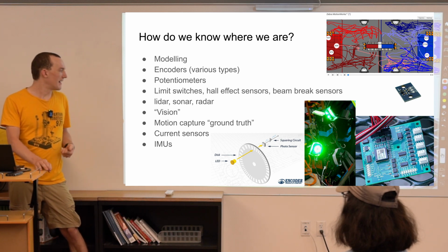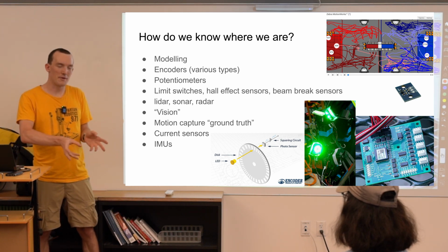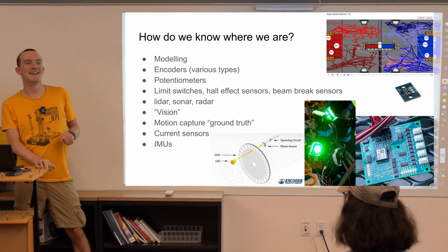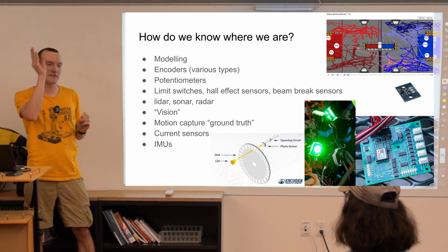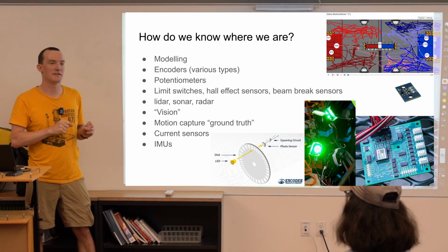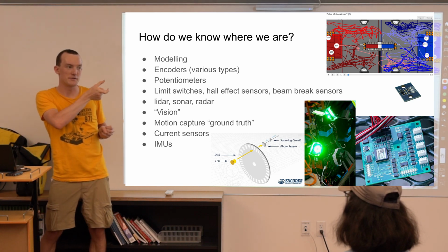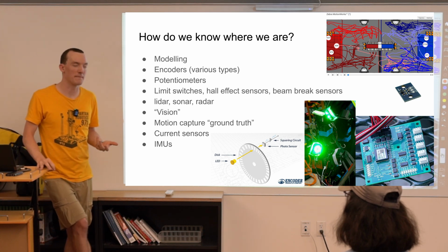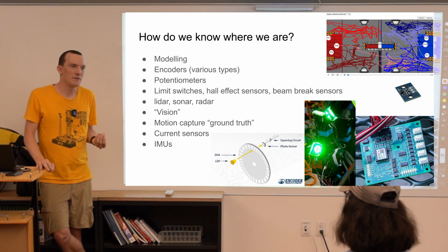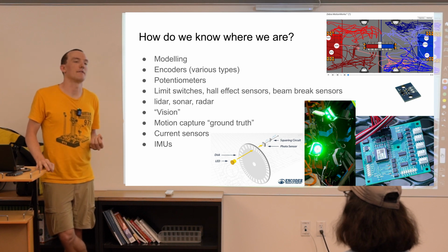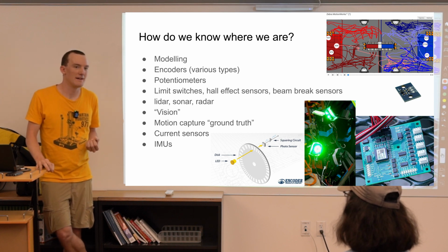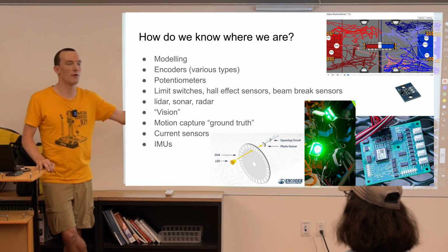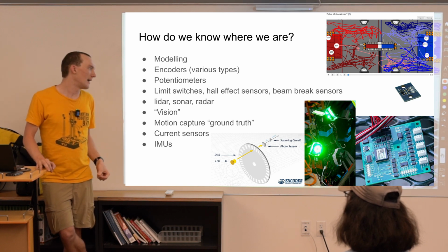So, as you said, the way an optical encoder works, you have a disk. This image, for some reason, does not actually show up properly. But you have a disk with a bunch of slots in it. You shine a light through it, and as the disk spins, those go on and off, and you can count those to see how far you've spun. This does not actually give you exactly how far the mechanism has spun at any given time. This gives you how many transitions between disk and open holes you have seen.